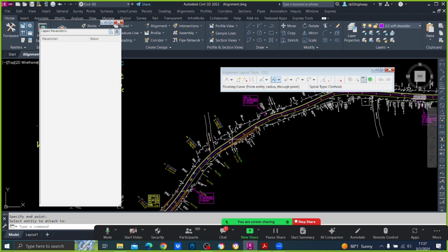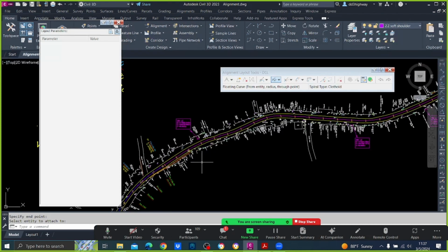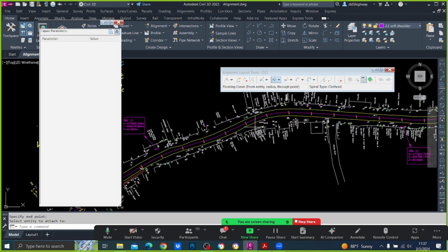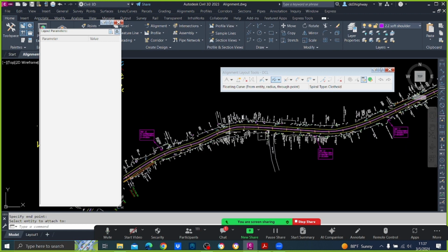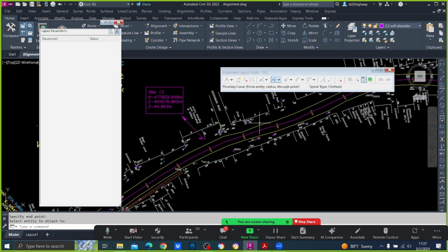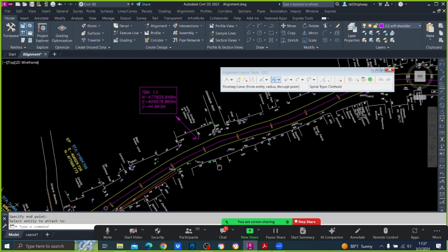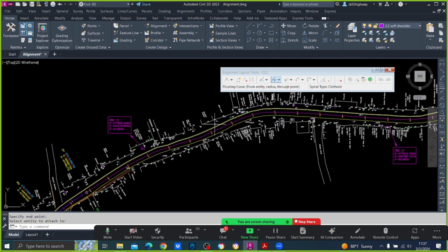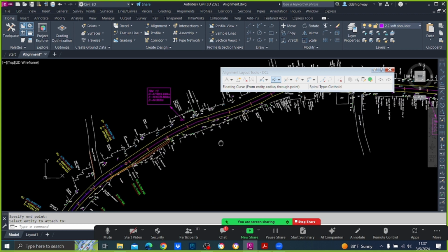Again there it seems like a small straight. Yeah, I don't like this kind of alignments here. So many reverse curves. Even when you consider safety also, these are not very proper. So it is better if you can have a straight like this. Shall we try that?